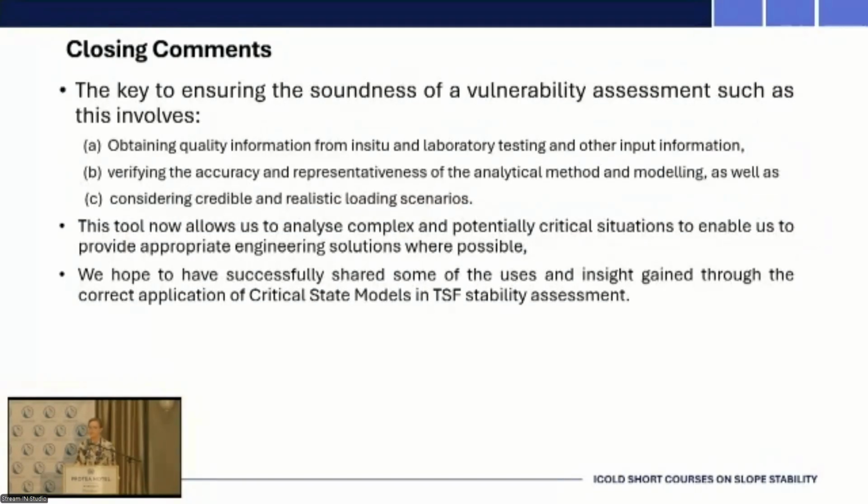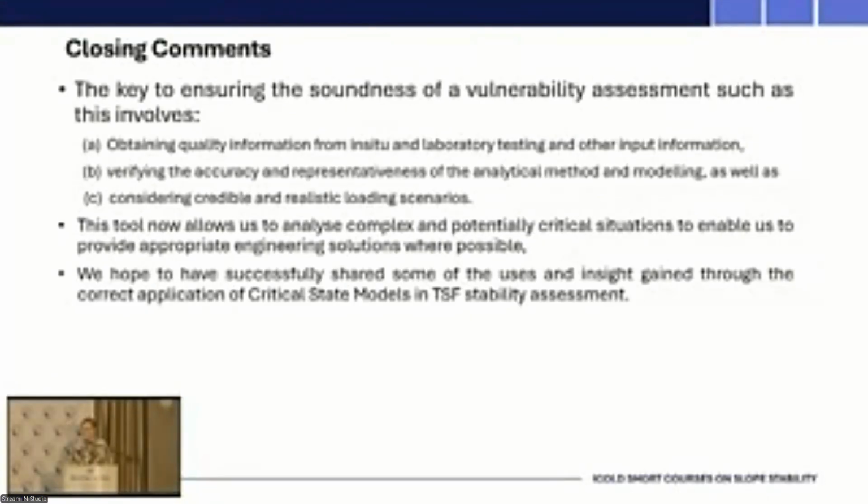The key to ensuring the soundness of a vulnerability assessment such as this involves obtaining quality information, so from in situ testing, lab testing, and all other input data, verifying the accuracy and representativeness of the analytical methods and modeling, as well as considering credible and realistic loading scenarios.